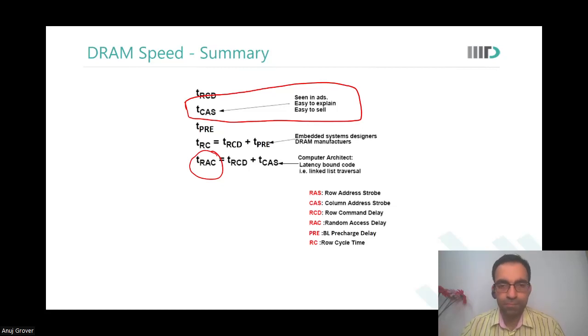So you said that the charge is done while reading only. Why is it a separate component here? So pre-charge is done after the sense amplifier information has been given out, and you no longer need the sense amplifier output, right? Only then can you start pre-charge. So it has to be a separate component, it cannot come inside TRCD. Yes, technically it is not. I thought okay. Got it. Right? It cannot come in TRCD.